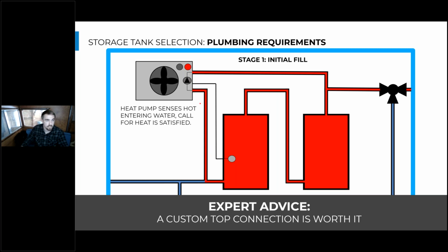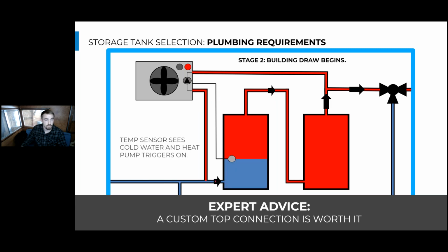So the heat pump shuts off, and then say morning time comes and everyone turns on their showers. So cold water is drawn into the bottom of this tank series, and hot water is pulled out at the same time and sent out to the mixing valve. As soon as that slug of cold water reaches the sensor that's attached to this heat pump, it sees a dramatic decline in temperature because we have those two separated volumes, right?